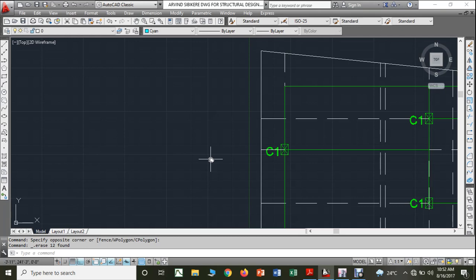But we will be keeping the width of all the beams equal to 9 inch here, which is equal to the width of the wall. We are not supposed to change the width of the wall. It will be 9 inch. Now the depth of the beam will be decided based on the L by D ratio, which we have considered in IS 456 2000.